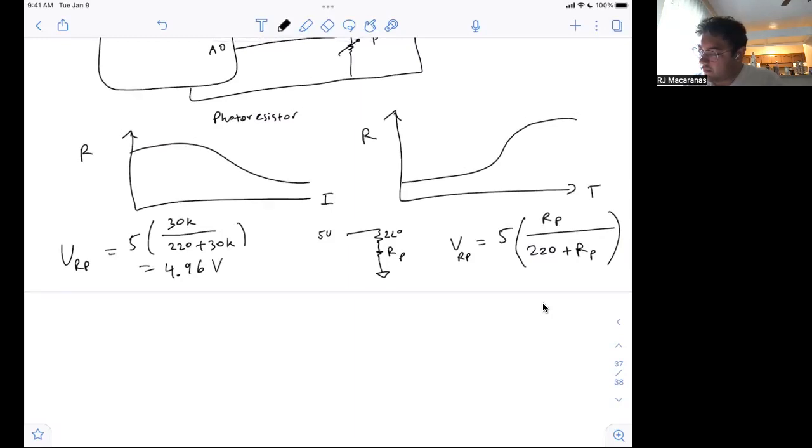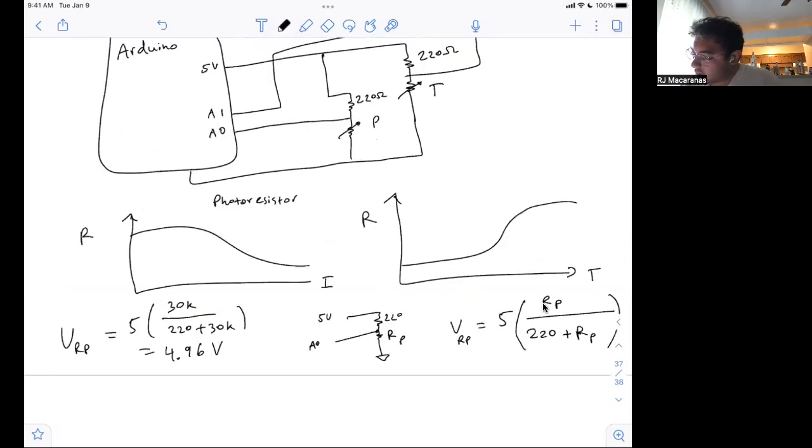And then since we have an analog pin connected there, right, so that's going to be right here, we have our analog pin. So our analog reading should then be however we convert that, right? So we take our 5 volts, I think, and remember, it's being mapped from 0 to 1023 for this analog reading.